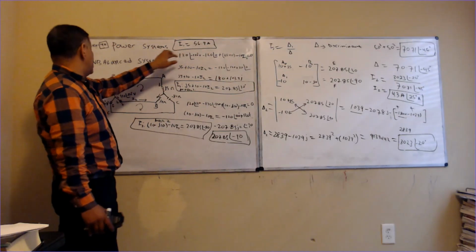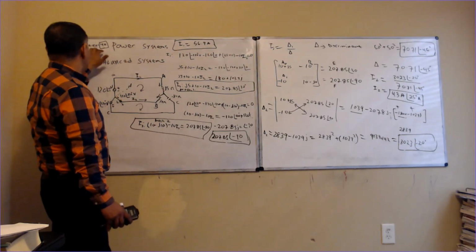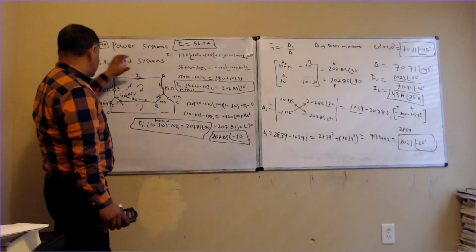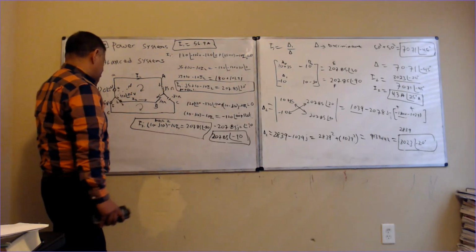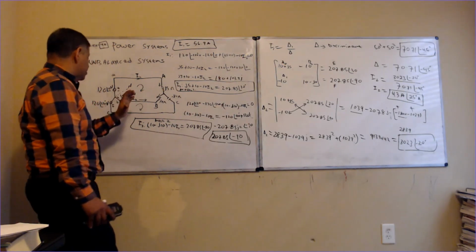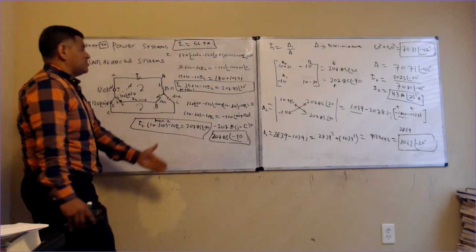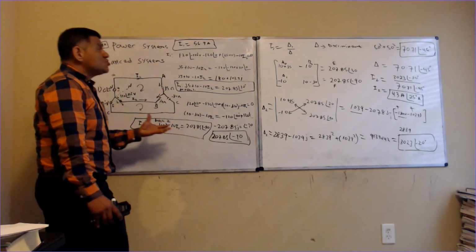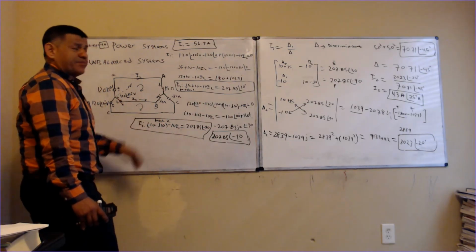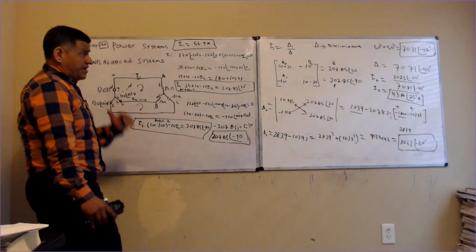When we have a difference of about 14 amps in current, and you do the math, the angle is going to be affected, and the power factor is going to be affected because the power factor depends on the phase angle. So it's going to create a lot of problems. When you have a lot of imbalanced load, it usually affects the power factor.